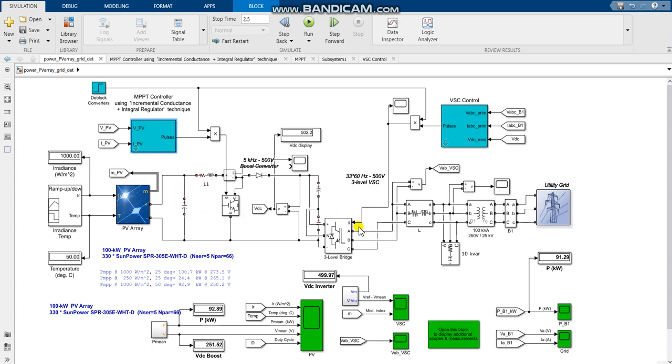The sizes of these components are important for the ripple of the current and voltage going through the boost converter, as well as to see if it operates in discontinuous mode or in continuous mode. Now, using a scope, we can analyze that by seeing the current going through the inductor.